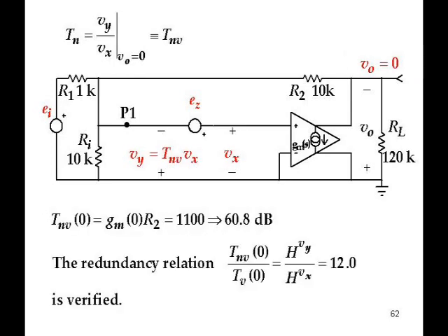Here's the fourth one. The null loop gain. Double injection again, but adjust EZ this time to null the output voltage VO. Start with Vx and follow it around the loop to Vy. Again, this is so easy you do it by inspection. Vx is multiplied by the GM. That provides the output current from the forward path. Now, there is no current down RL in this case, because RL has 0 voltage across it. We've nulled it on purpose.